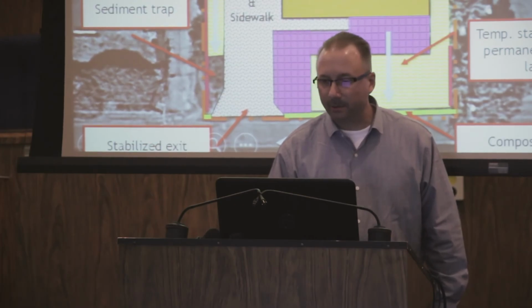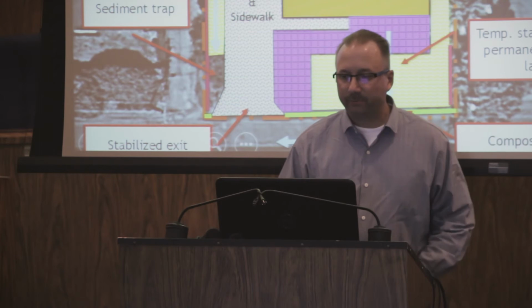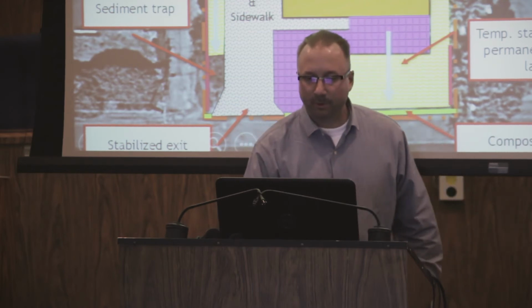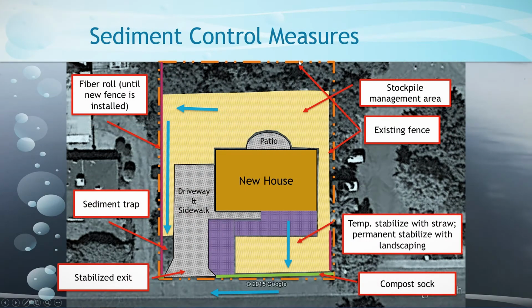Stockpile management area here in the backyard. Our existing fence for a portion of this east side, and I may or may not have drawn that far enough down, and then for the back, that's going to be our sediment control. No need to put anything else there. We got an existing fence that's going to stay there. That is a good sediment control.